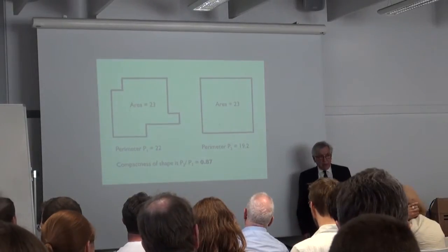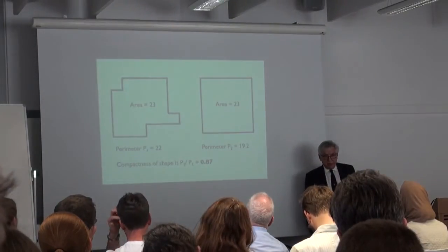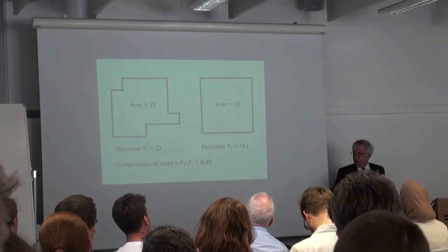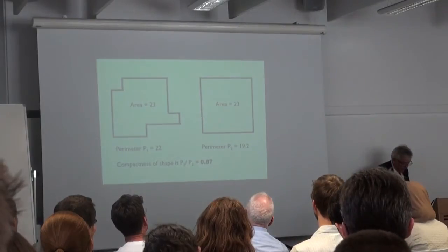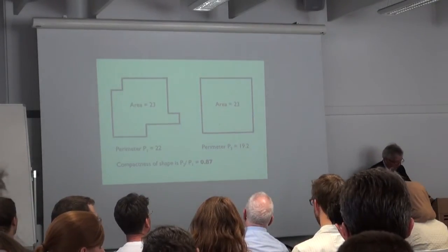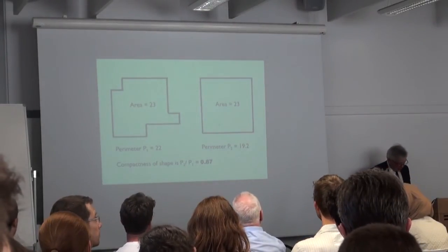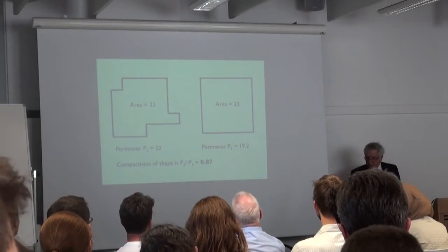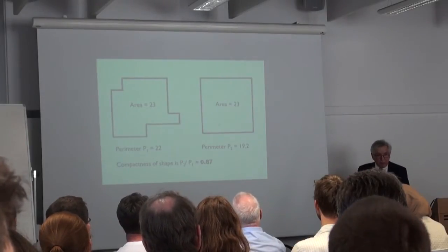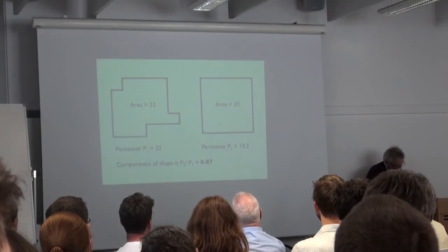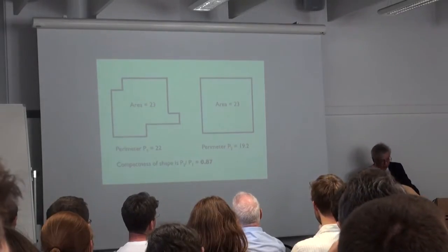This kind of measure of compactness was used by a group of architectural researchers at Strathclyde University in the 60s, applied to schools, and later on we're going to see some work applying these compactness measures to schools. So these 3 measures, surface to volume, volume to wall area or plan depth, and compactness, are clearly interrelated. For example, buildings that are less compact would tend to have more wall for a given volume. But they can all be useful in isolation or together for looking at relationships with energy use.